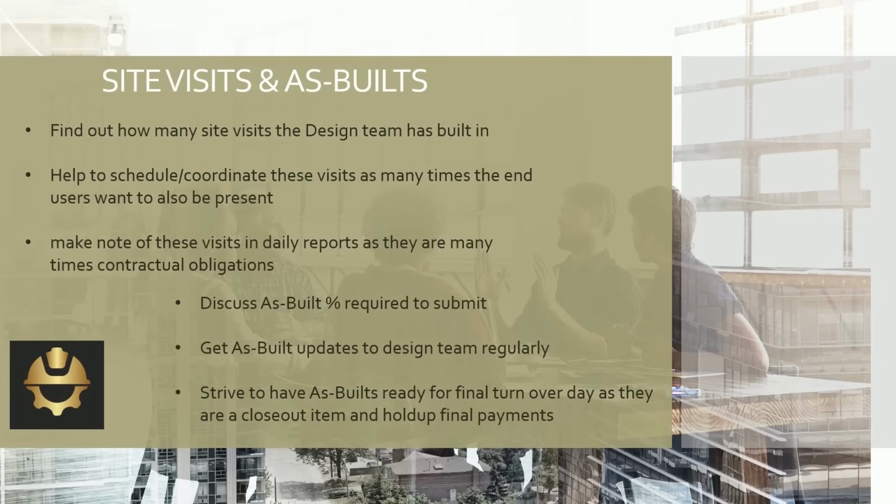Yeah. So the end result is still the most important part. That's right. Getting them in per your deadlines. That's right. And a little caveat to this, if you are also not staying up with your subcontractors and forcing them to do the red lines, so they can be updated into the as-builts, you don't want to get caught having to do 3, 4, 5, 6 weeks worth of red line updates with your subcontractors. Absolutely. Especially if they don't remember what needs to be redlined, you're in a bad spot.